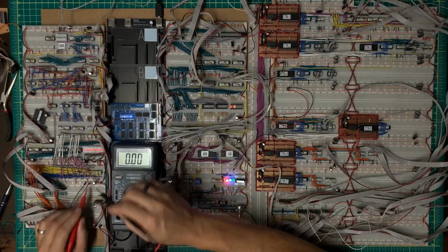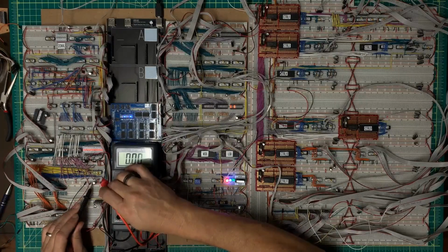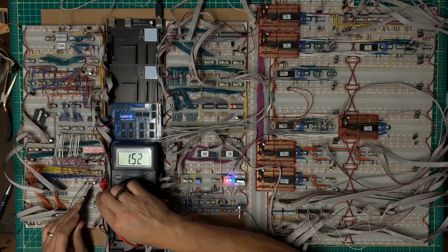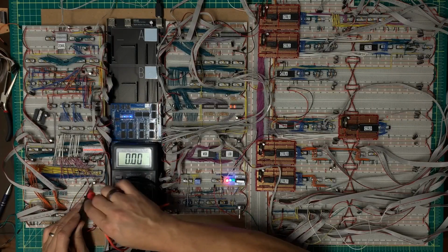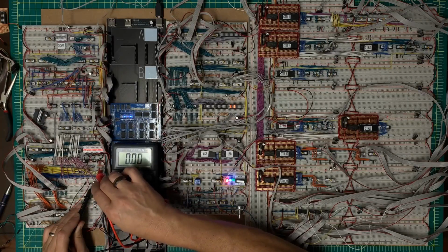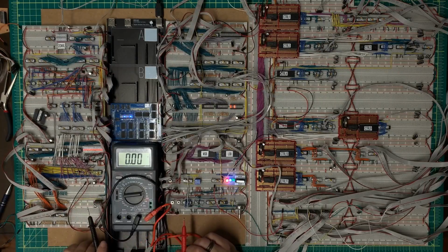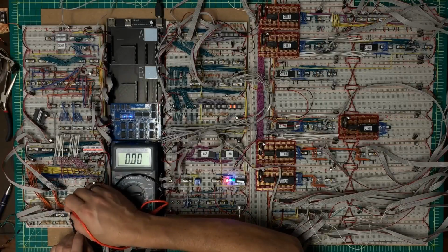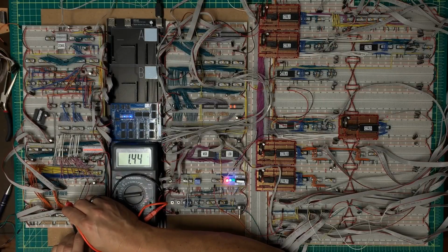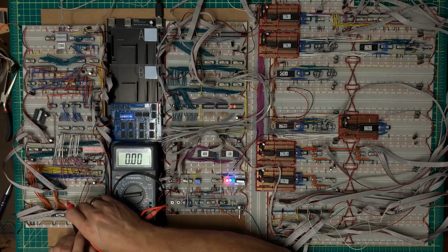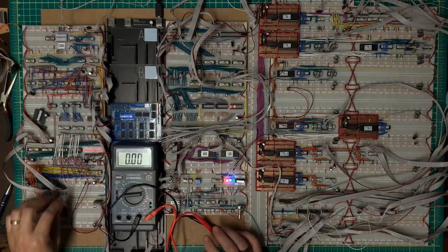And one of the things I noticed is that the A input on the least significant bit of the adder, coming off of ALU A, is up here and they're tied high and low. But it's 1.5 volts coming out of the input pin. And if I look here at the 10,000 ohm resistor, I've got a voltage drop over that of 1.44 volts. The resistor is not overcoming or pulling that signal low.